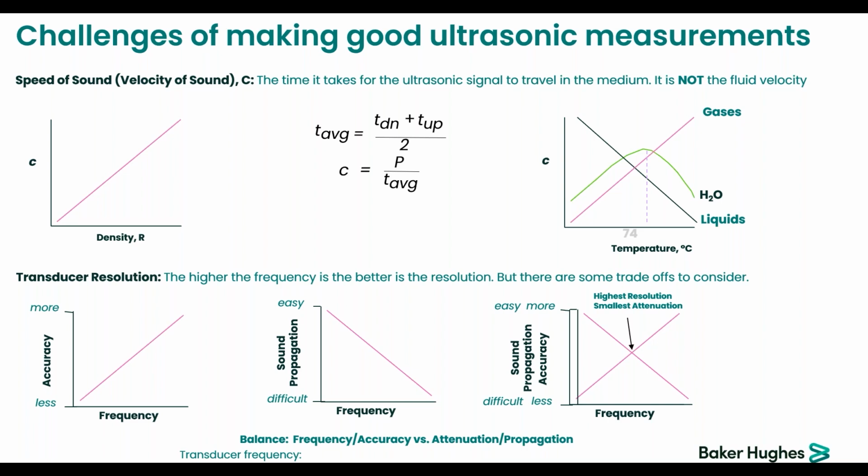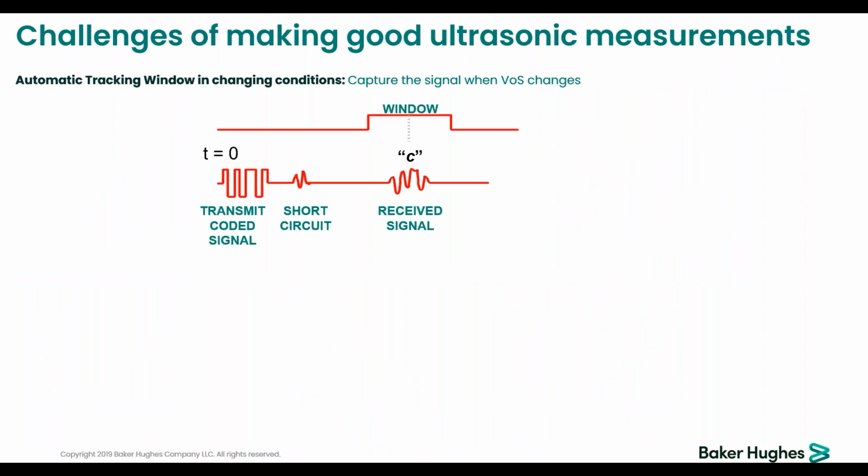If it's gas, you start only at 1 meg and then you will decrease the frequency when the pipe goes up, as well as when the pressure goes down, because the sound will not transmit as well in low density as in high density. So with all this, we have a very large spectrum of transducers with different setups to address this.